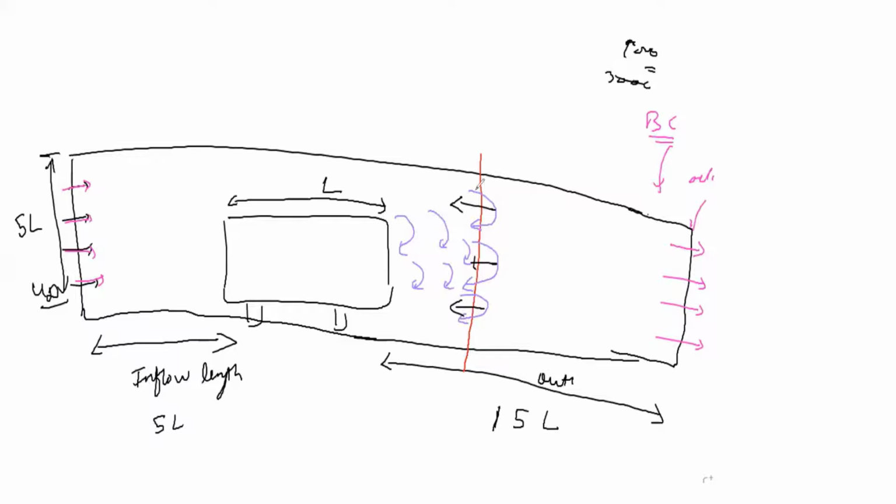But your boundary condition is saying it should be like this. Now your simulation will give you very wrong, very vague results, or it might crash also. Is this point clear? Yes, sir. Right? Outlet means you are telling the solver that this is the outlet, and the meaning of outlet is that your flow should come out of the volumetric domain.